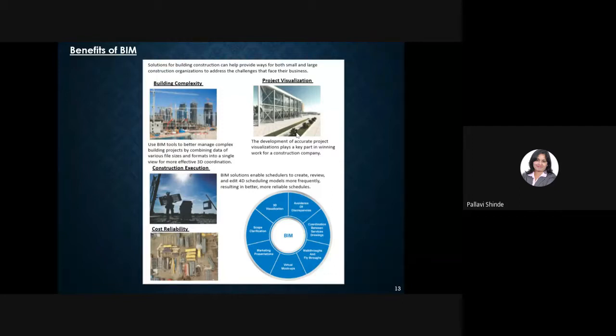Coordination between services and drawings as well, because for critical services, it's not enough to only create 2D drawings. It requires a lot of coordination for MEP services, plumbing services, firefighting, all of the water hydrants, all the multiple services which we are using. So coordination between multiple services is very important. And then not only a coordinated model, but coordinated drawings as well, which are going to go on site as a coordinated output. So avoidance of discrepancy, yeah. Suppose some issue comes on site, we have to stop the work, we have to go there, we have to attend.